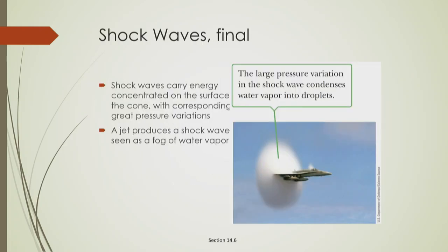If you really want to have fun, you can go out on the internet and look at shockwaves. They're everywhere. You can see different planes. What's interesting is this one up here. It's usually their air speed monitor. They have a little pitot tube up there to help them see their air speed, and that point will usually also generate a shockwave.